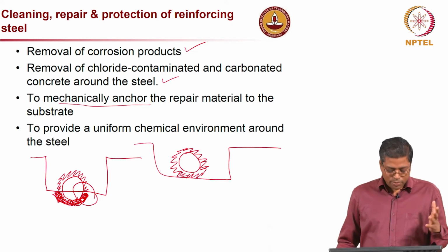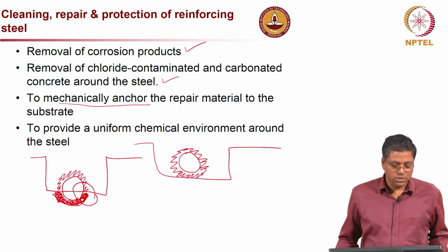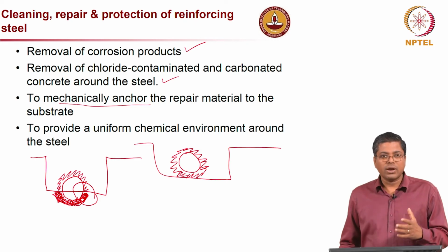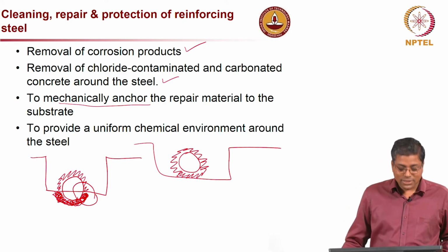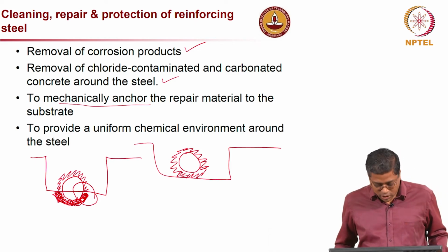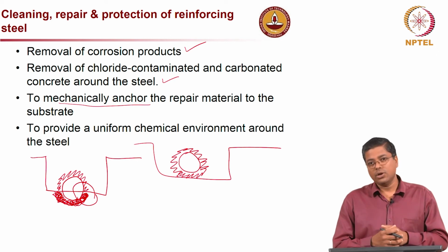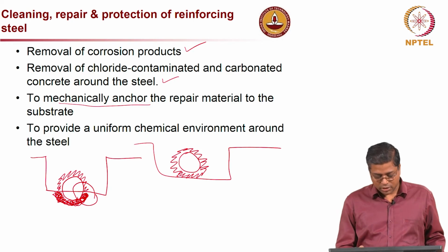So, let us stop doing this patchwork when there is corrosion. Do the patchwork in a proper way, do proper undercutting and then place the proper repair materials, and if necessary also adopt cathodic protection, so that the repair will be durable. A durable repair is our key objective here.